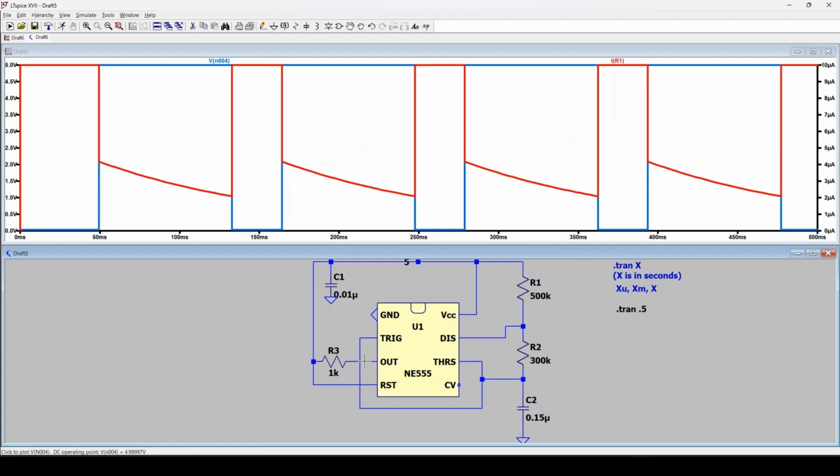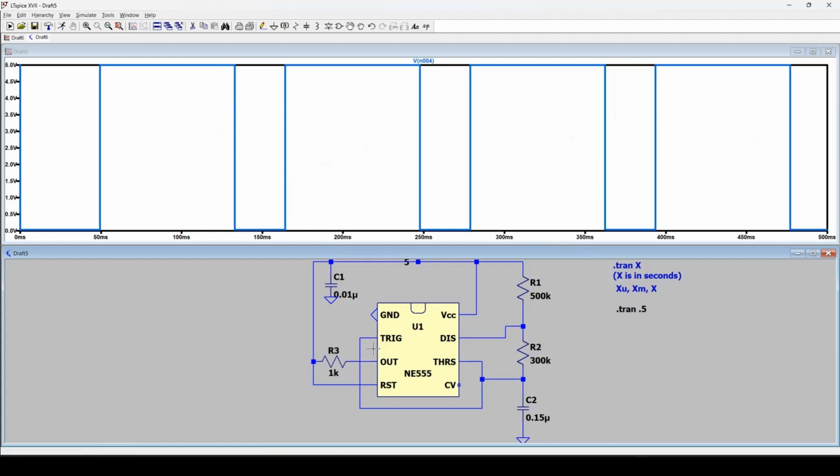All right, so now back to here. Now let's say we wanted to do something similar to our .op measurement, where we're taking a differential measurement. So we're taking the measurement of something relative to something else. And we can do that by simply going over the node that we want to measure. So the voltage in this case that we want to measure, click on it and hold, and now move to our relative point. So this is our second differential measurement. In this case, I want to measure it relative to the output, and I'm going to let go.